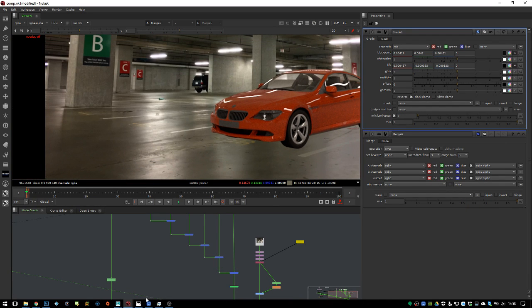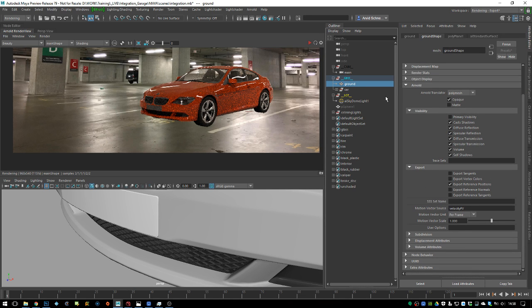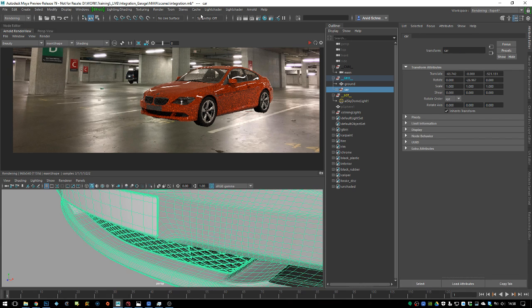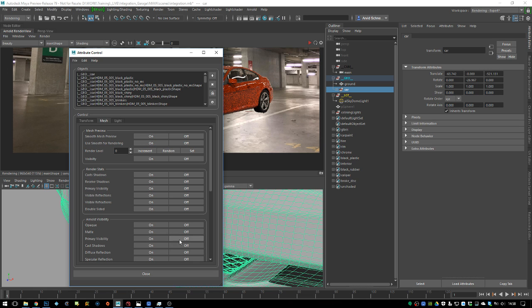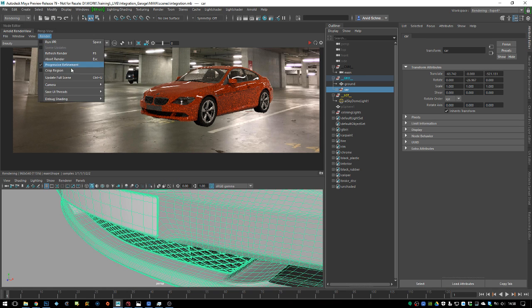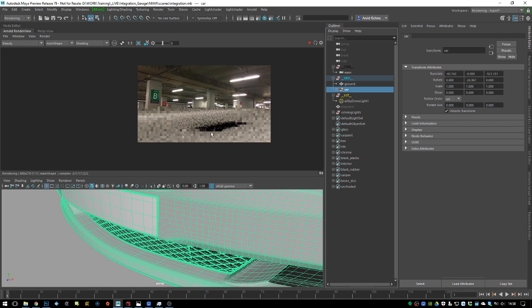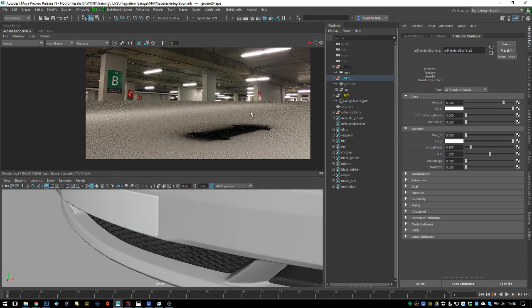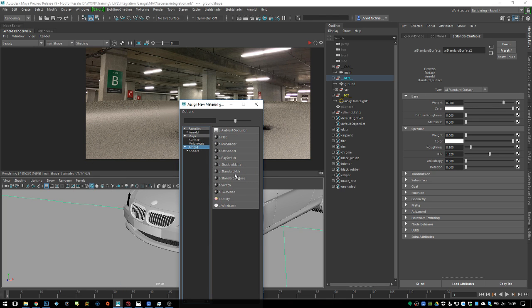And obviously we are missing the shadow, so I will be rendering that out pretty quickly. I'm not creating render layers now, so I will just quickly do this in the IPR session. So the ground is primary on, and now all the cars should be primary off. I will use my UI again, attribute control, and everything gets primary visibility off. Let's save and render. So we should just get the floor now, hopefully, which we do get. And then the floor will get a new shader, which is the shadow matte shader. There it is.